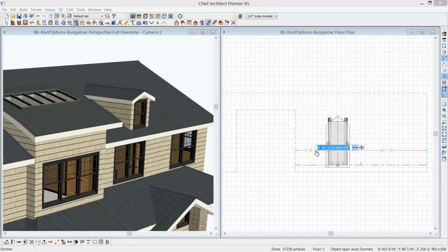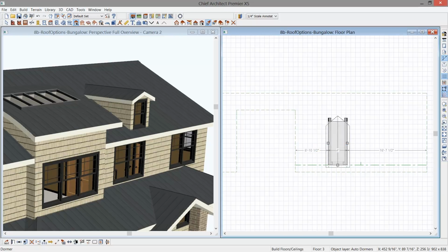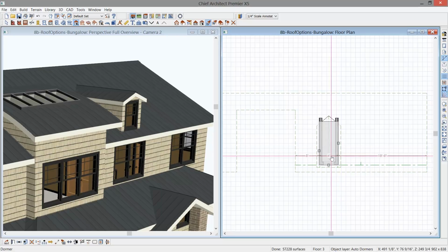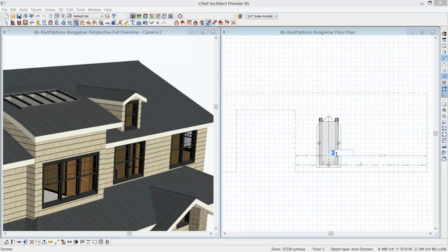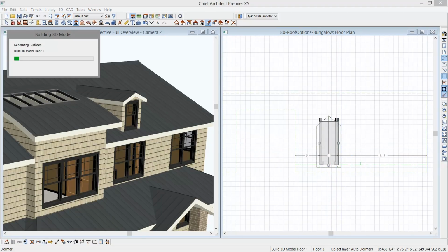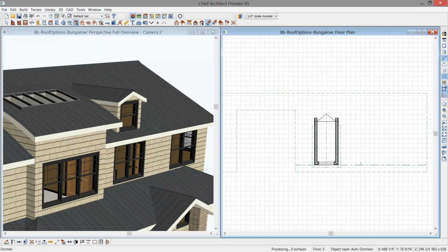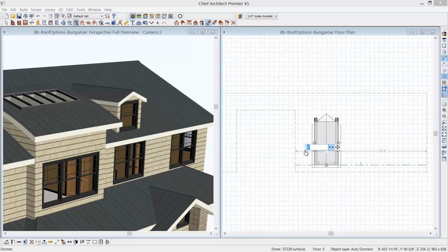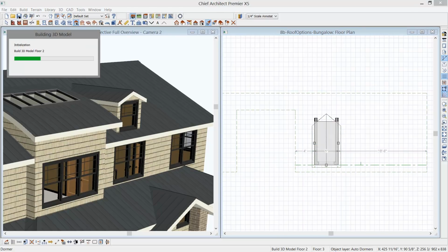So if I want to set that 5 feet off of the shed roof cutout, I can select that dimension and it will move it to be 5 feet. You can also click on the other dimensions if you want to highlight this. Let's say we want that to be 5 feet wide. You can select it. Any of those dimensions you can set up that way. Let's go ahead and move that back over now that we resized it.